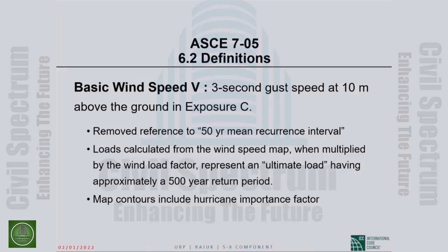When that load is factored up by the wind load factor, which today is 1.6, that factored load has a return period of 500 years.